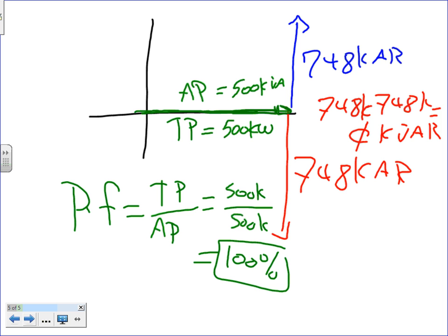So by adding a synchronous motor in your building, like the industrial building that we have, they add condensers, a big synchronous motor, basically one or two, and you can size it in kVARs. You solve the problem of your low power factor. The most common ones that I'm familiar with are capacitors.